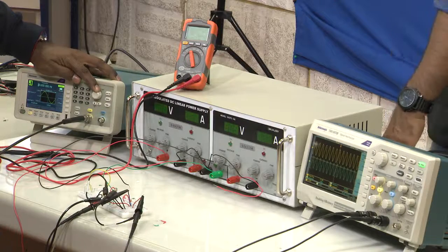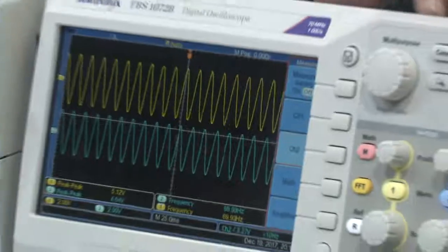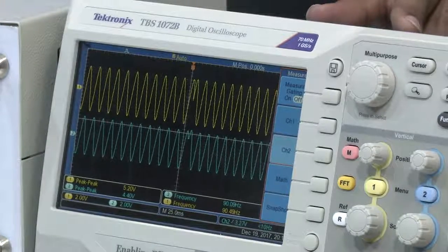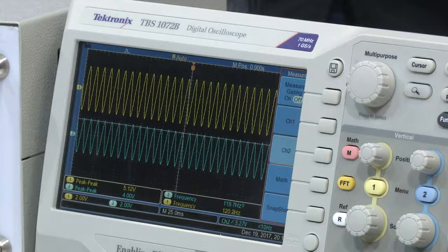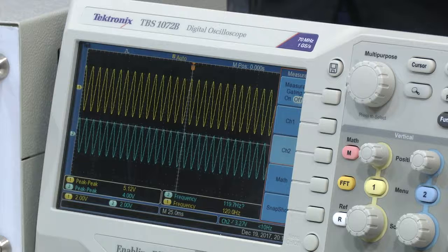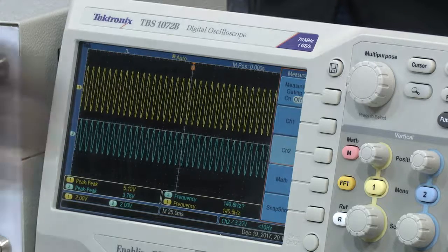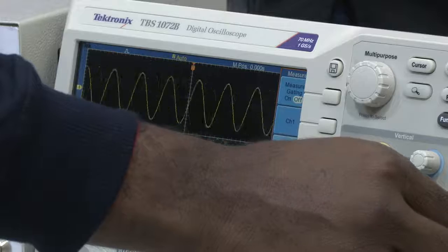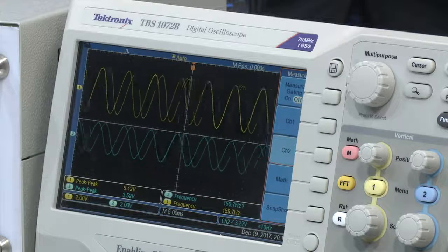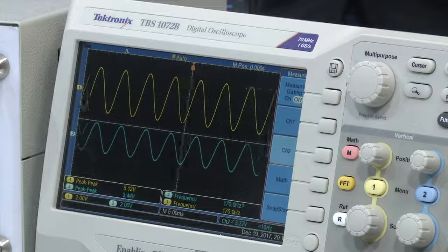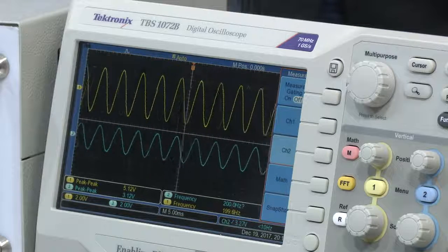Okay. So, we are increasing the frequency to 60 hertz. You can just look at the oscilloscope, he is increasing to 60 hertz, 90 hertz. So, slowly 100 hertz, still you can see it is following, 119, 120, still following 120, and now 150, and suddenly you see that the amplitude is getting clipped, or the amplitude is decreasing, right.